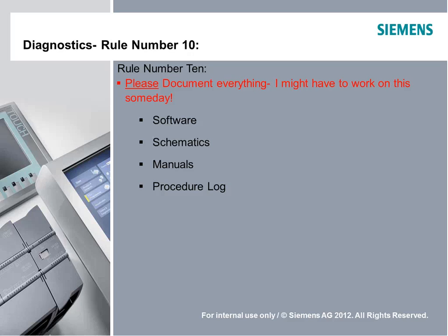And treat the cause, not the symptom. So you may have to fix some things that were broken by the cause. In other words, we may have spikes and so forth that blew up an I/O module, or you may have a solenoid valve that dead shorted and actually took out the I/O module, but you need to replace everything and get it all back to where it was working in the first place.